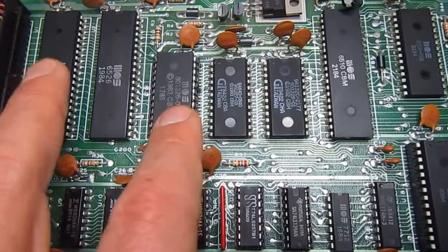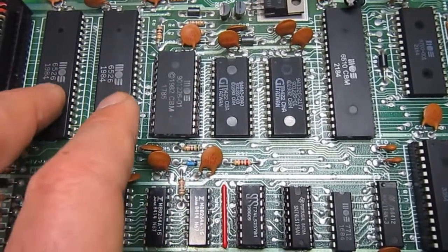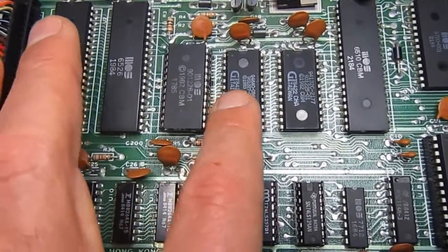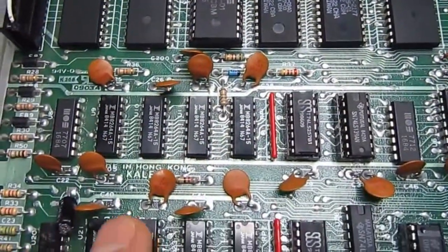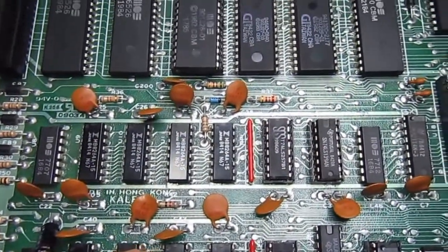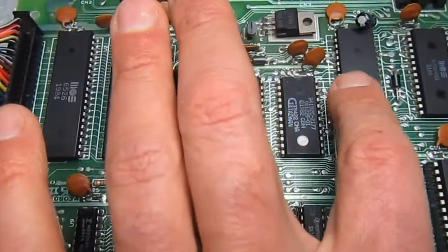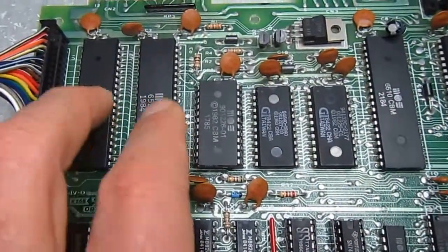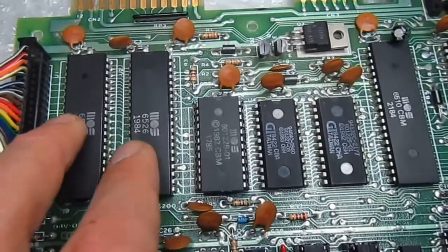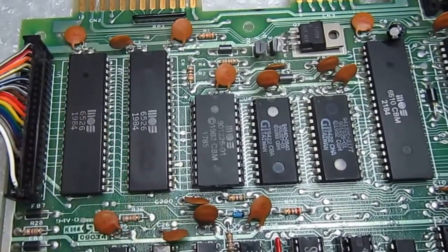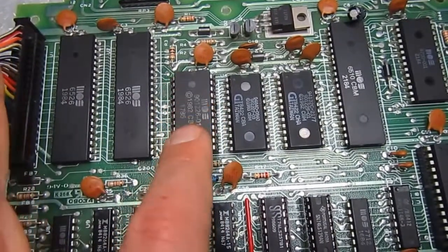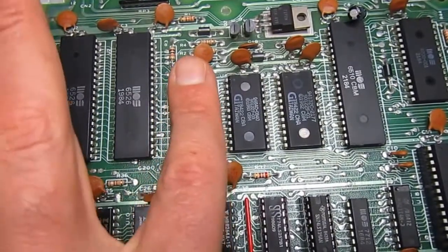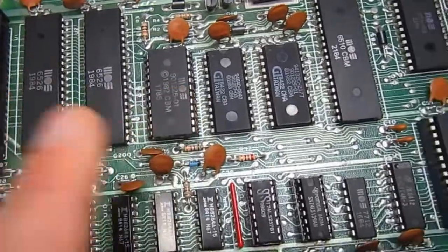That was amazing, that no CIA failed, no kernel ROM, and no CPU failed. Also no RAM, because every access that the CPU made, these two guys were also answering and driving the data bus. So that's pretty good as a result that we had only to change the basic RAM after this kind of failure.